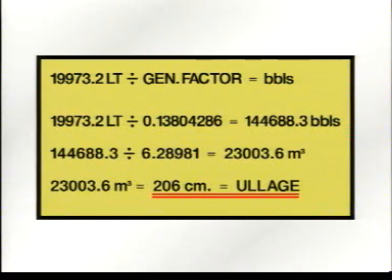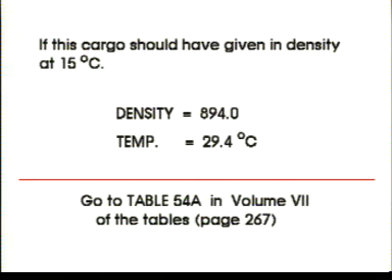If the same cargo were given in density, at 15 degrees centigrade, and with the temperature measured in centigrade, you would have worked in cubic meters and metric tons. You should never jump between API and density. We will do this conversion only as an example. We use the ASTM tables to convert API to density and Fahrenheit to centigrade.